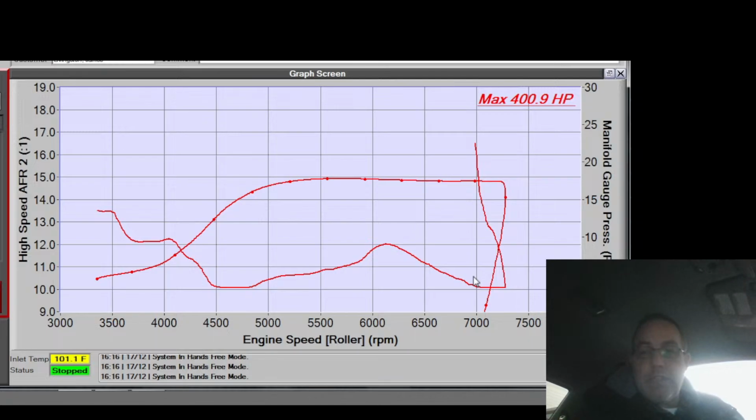And the idea is that we want to make sure that whatever heat range it is, it's enough that they get clean. Now, in a race environment, as long as the race happens, even really cold plugs will clean, because there's a really high duty cycle, lots of combustion events, lots of heat, lots of BTUs being released by repeated high energy combustion events. It's going to heat up that little dangly piece of metal in the cylinder, right? And it's going to get glowing red hot and burn the carbon off of it. Same for the insulator. The ceramic is going to get hot and burn the carbon and other stuff off of it. And that's why plugs look the way they do.